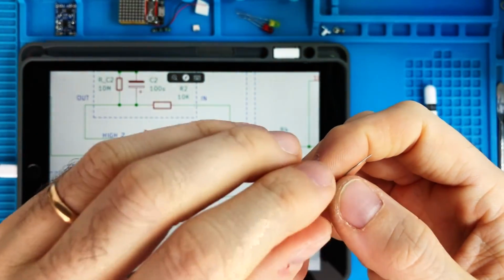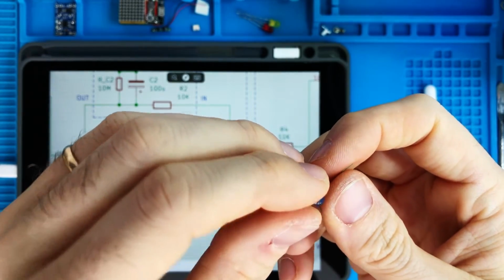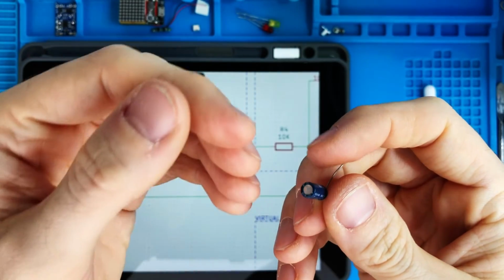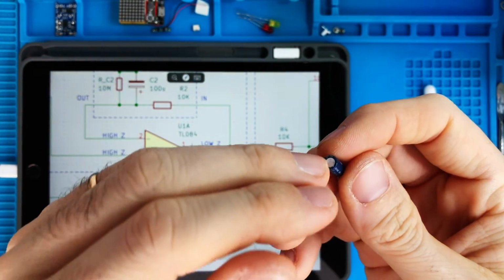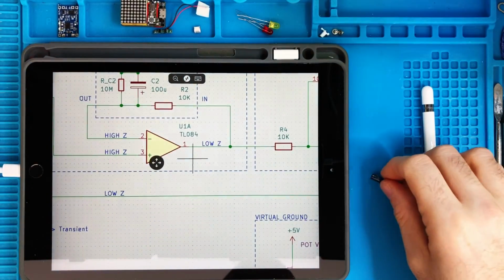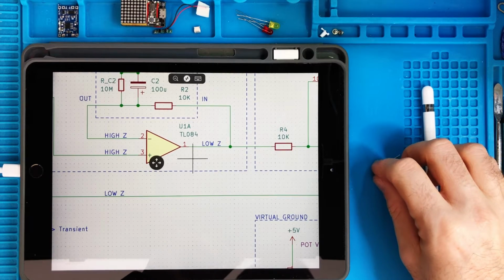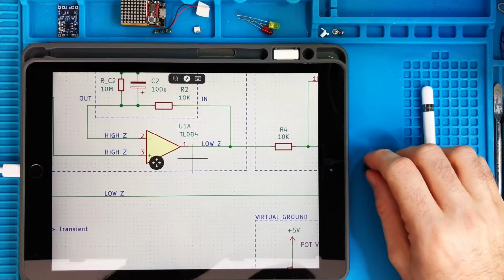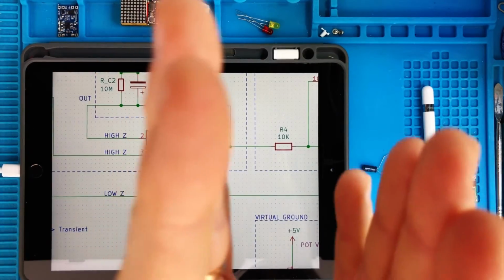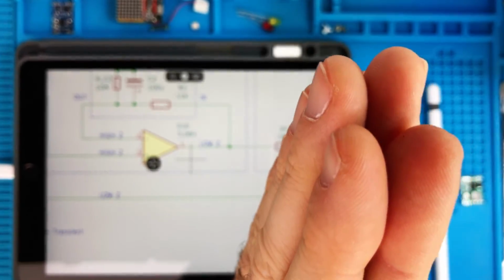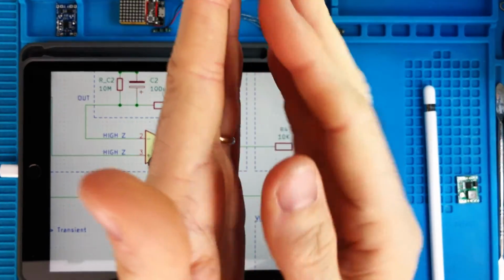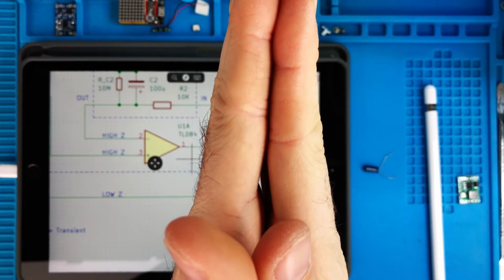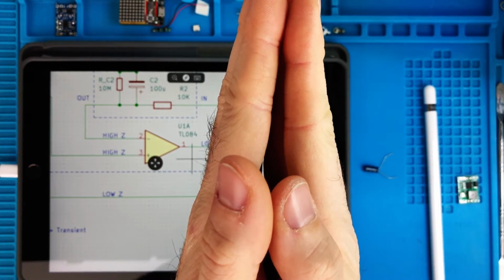And then this layer of oxide is created by this electrochemical process, applying a voltage here, and this is an insulator, and it's a very thin layer. So if you remember, the capacitance of a capacitor is inversely proportional to the distance of the plates. So if you put two plates very close to each other like this, and in the middle you have an insulator, which is this layer of oxide, then the capacitance can be very high.